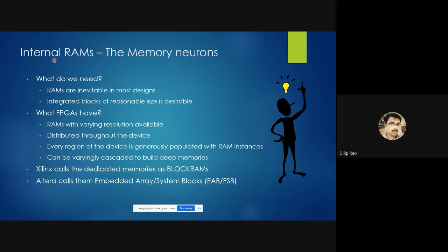Okay, and also, as I said, these are the block RAMs, but there is also another method of instantiating memory. They are called distributed RAM. The distributed RAMs are not dedicated memories, but they are built out of the memories that are intended to be used for a LUT. Like how we were saying before, there are memory elements which hold the truth table for combinational logic. So they will be interconnected to build a bigger memory. That is what is termed as distributed RAM.